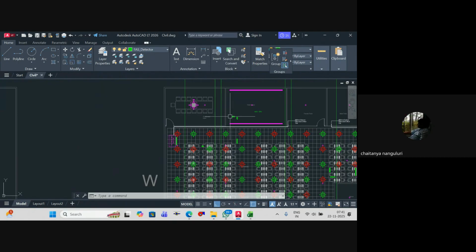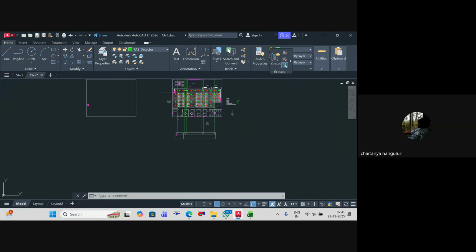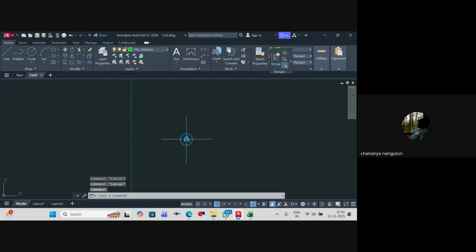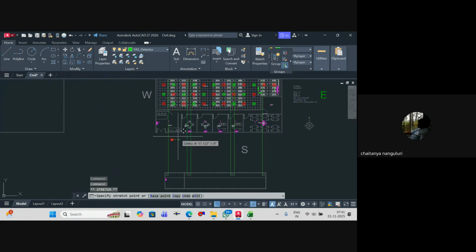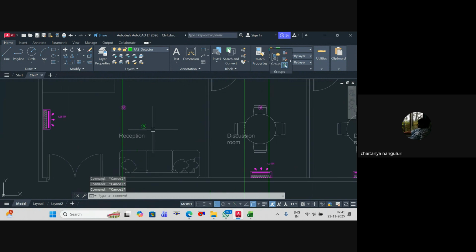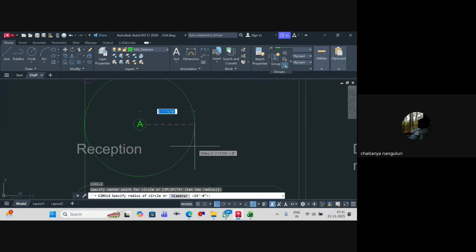So we need not worry. We'll take this above false ceiling, except toilets, because only toilet walls will be block work installed up to the slab, and the server room will be taken separately. For the rest, it's not required. So we'll directly take a gap of 7,500 mm.